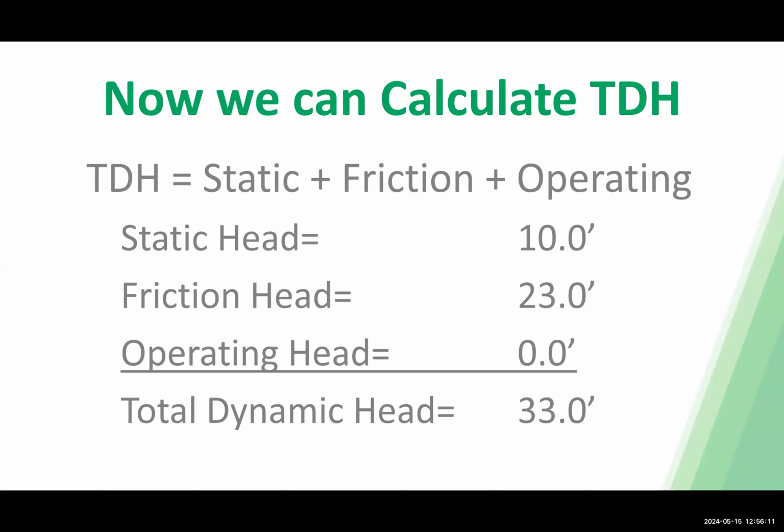But the runtime isn't necessarily what we're worried about. We're more worried about how often that pump is turning on and off per hour. So like I said before, about 6 to 10 starts per hour is a sweet spot for most pumps. Just because as you get up into those higher numbers of starts per hour, that's when it can become problematic on that motor, starting so much.